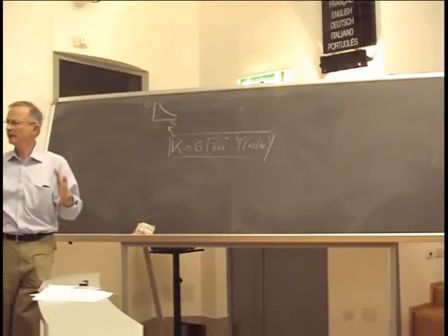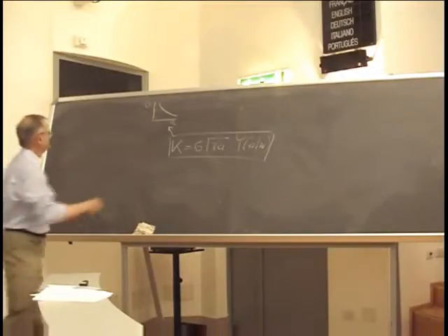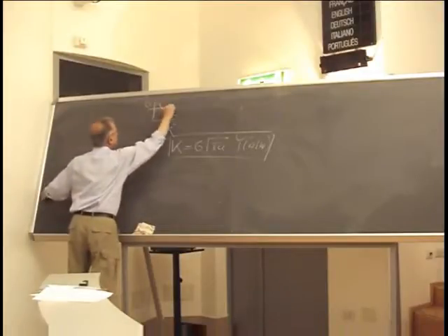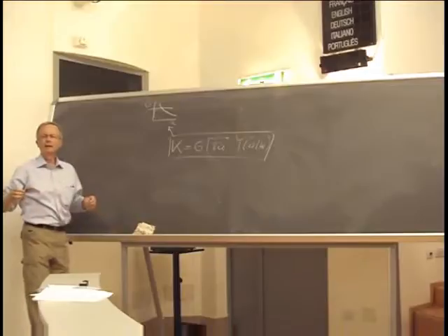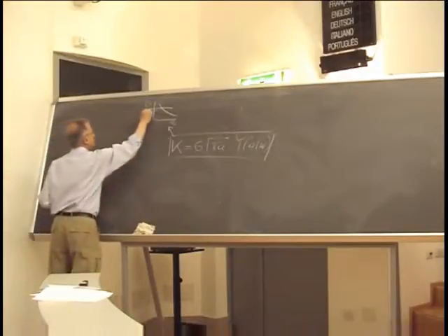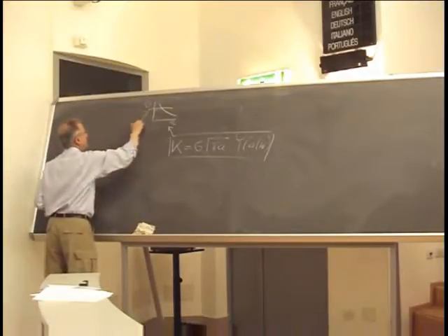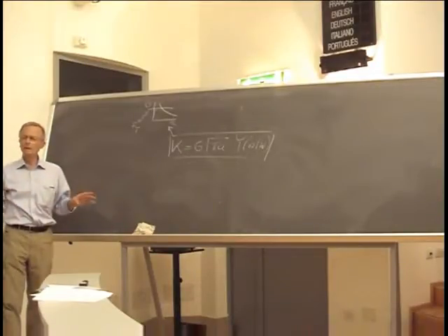What sometimes happens, and the bad news is that you are on the unsafe side. So you need to know the yield force here, which in a tensile panel is no problem, but when you have a complex system, you have to determine the yield force or moment or whatever it is. Please, you don't make this mistake.